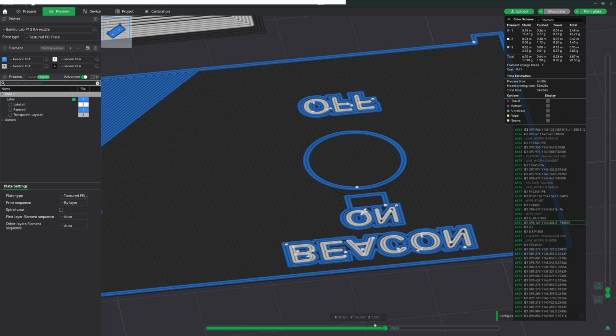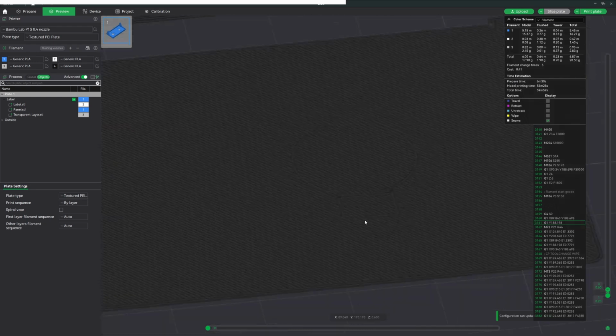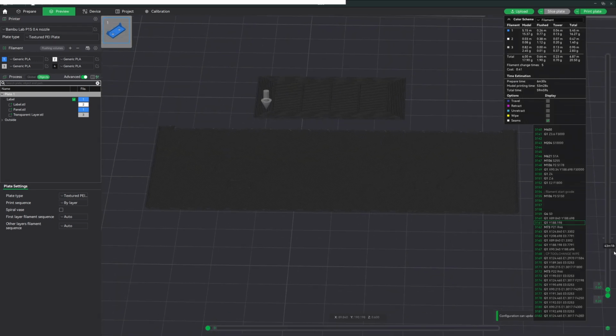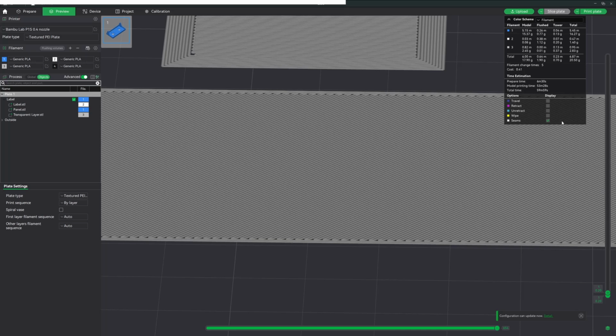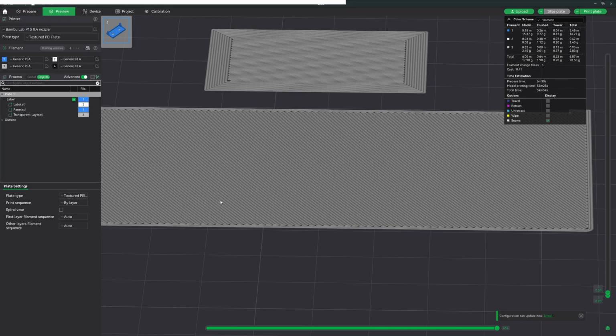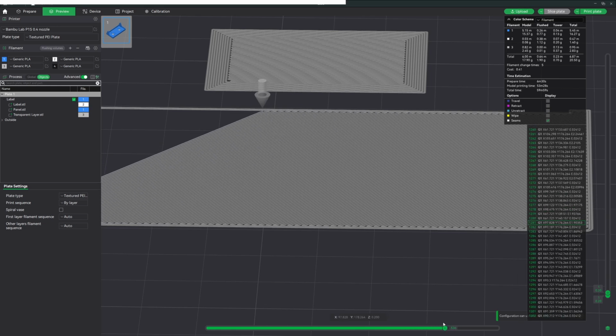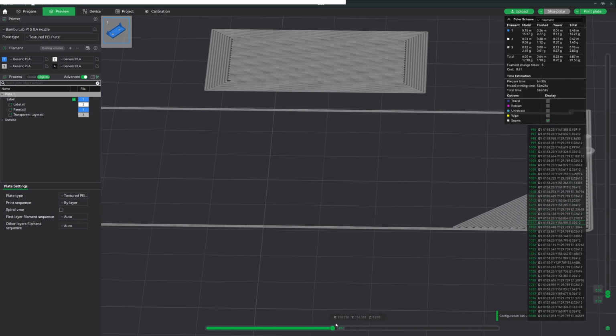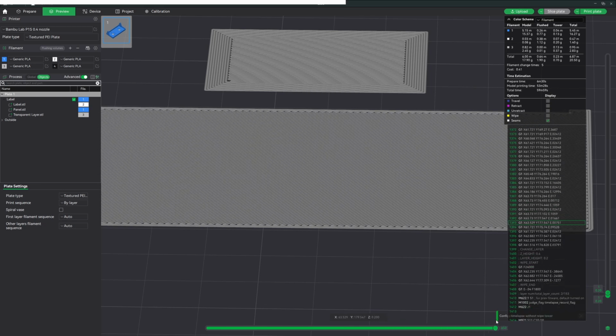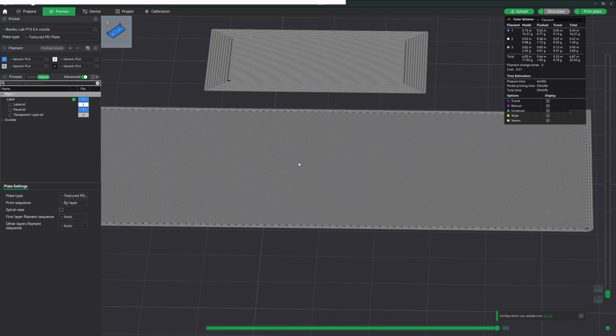So in order to get a really nice flat surface on the transparent layer, we created this layer without any holes in it. So it's a nice, continuous motion inside this first layer. That's the reason why we don't create the holes in this transparent layer. We will just cut it out with a knife after the printing process.